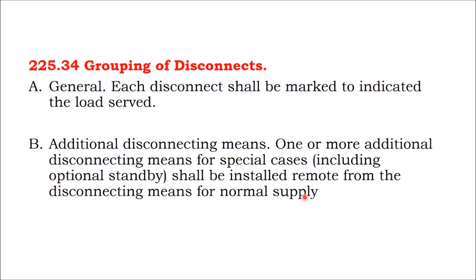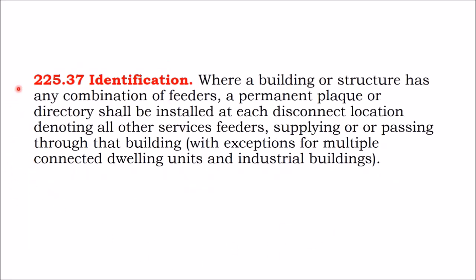They need to be clearly marked and labeled. And while they need to be away from the normal building, I would think they would still need to be within sight from the normal building with a placard, just to indicate to the first responders what exactly is going on and what switch does what. There's a third-party switch you can buy. Midnight Solar makes it. You press the switch, that de-energizes everything: your solar rapid shutdown, your battery breakers on the service panel. The whole system turns off.